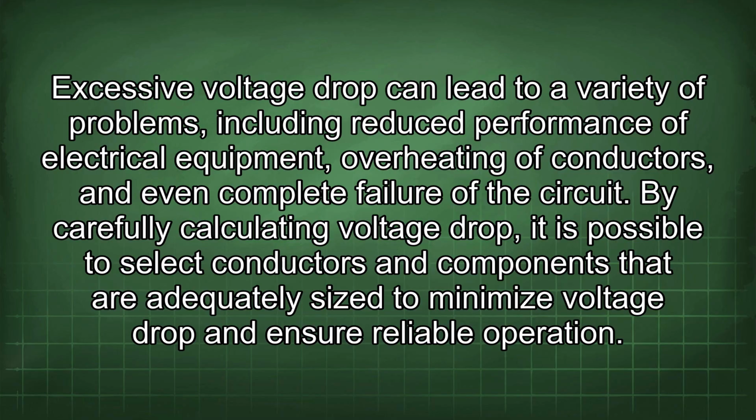Excessive voltage drop can lead to a variety of problems, including reduced performance of electrical equipment, overheating of conductors, and even complete failure of the circuit. By carefully calculating voltage drop, it is possible to select conductors and components that are adequately sized to minimize voltage drop and ensure reliable operation.